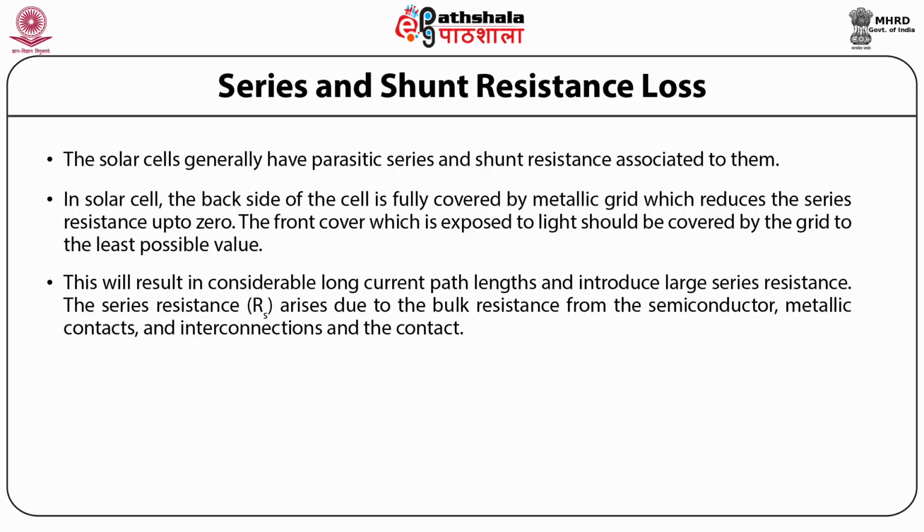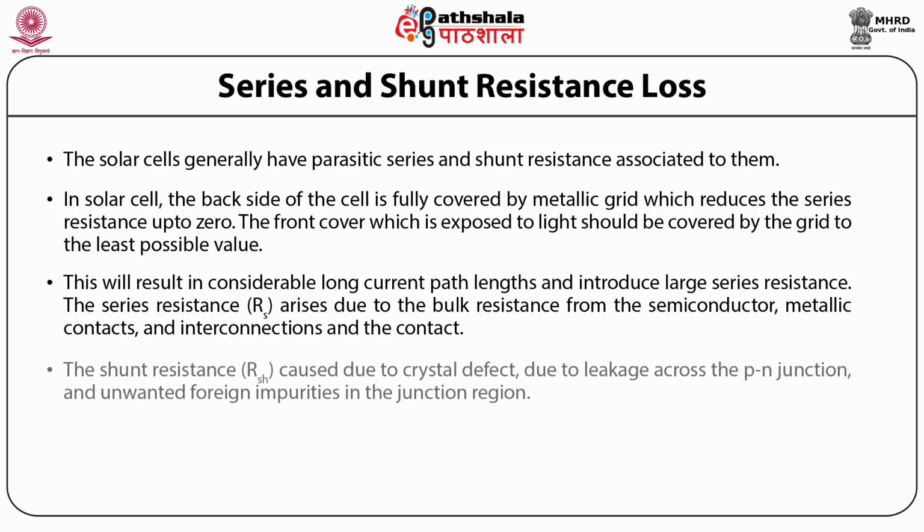The series resistance RS arises due to the bulk resistance of the semiconductor, metallic contacts and interconnections, and the contact. On the other hand, the shunt resistance, that is RSH, is caused by crystal defects, leakage across the PN junction and unwanted foreign impurities in the junction region.